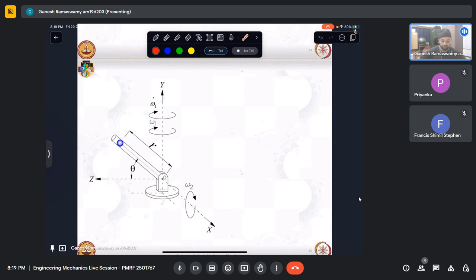So the idea is, first you look at a question, see how it is constructed. Look at the first rotating member over which other rotating members are mounted. You sit on the first rotating member. Now you are in a rotating frame of reference with some omega you yourself have. Now you are perceiving things relative to you, which will be AREL and VREL. You just need to account for all the motions that you will perceive. Then appropriately apply the equations, it should be straightforward. Only thing that becomes a little more involved is that the cross products are three-dimensional, so you need to go by the determinant mnemonic. Other than that, there is nothing very different here.